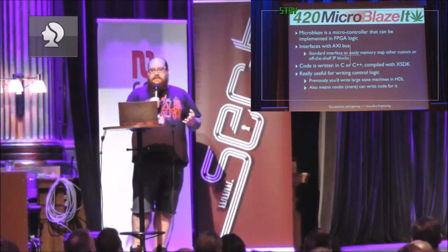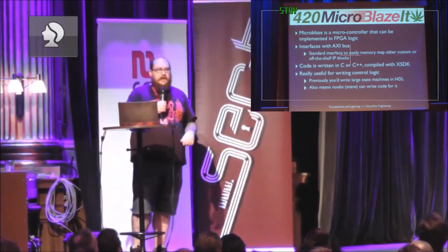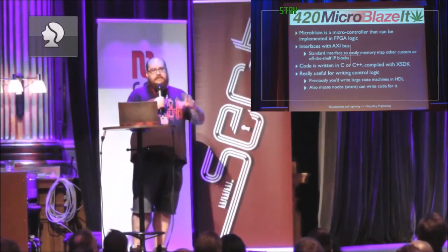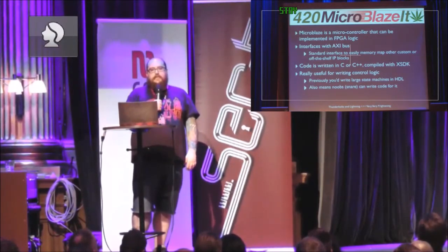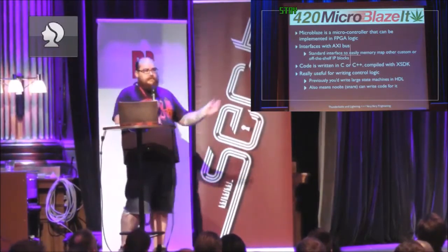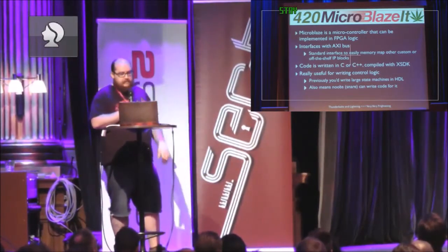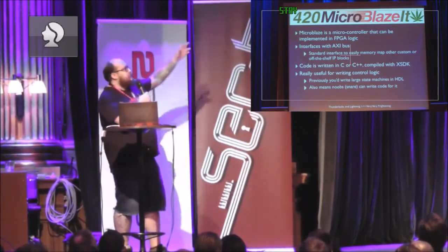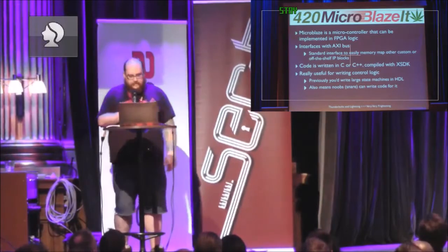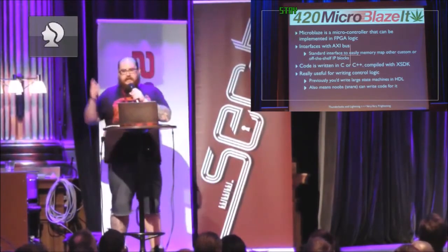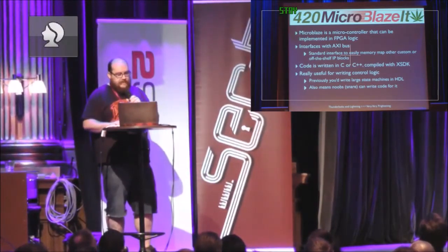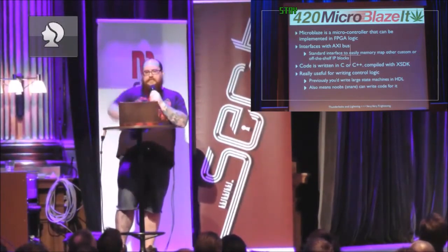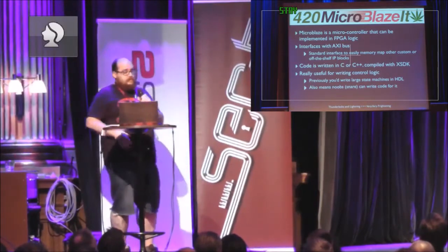Otherwise you have to write a state machine in VHDL or Verilog, which is relatively time consuming for things that should be pretty simple, like writing a little loop in C. You have to write this big state machine in an HDL, and then it's very difficult to debug. So yeah, it also means noobs like me can write code for it, which is great. So I don't have to rely on Sam to do his ChipScope magic and look at the square wave output and go, yes, that's a completion packet with an error, while I go, what?